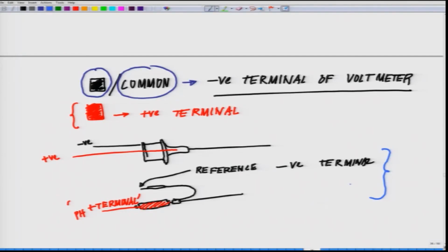And when a pH meter with a BNC socket is used, the center of the wire is the positive input, as I showed you, and the outer connection is the negative output. So, this is basically about the BNC cable. All the standard BNC cables are like that. So, keep that in mind. These are some of the practical knowledge I wanted to put forward.